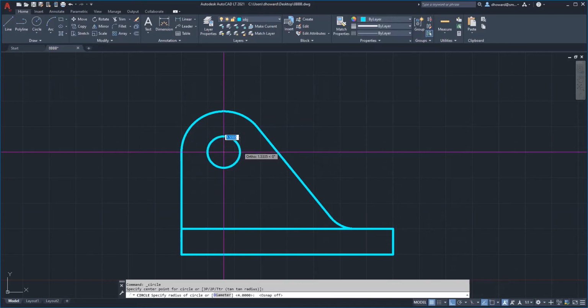I'm just going to snap to grid, F3 to get object snap off, F9 to get the grid back on, and I'm just going to snap to grid and pick one of these squares. I guess I'll go with that one. And then draw another circle down here, sort of randomly placed closer to the bottom, and make it the same, and then connect them, L, enter, connect these guys, and then trim that out, TR, enter, get rid of this, and get rid of that. There's my slot.